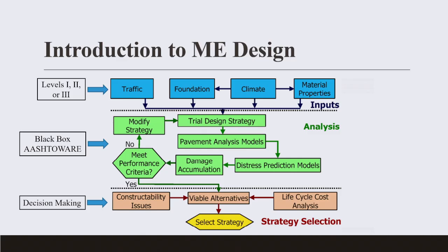I know under the ECOWAS project, PEL, you know, PEL Consort from Nigeria, I know they tried to use MEPDG for some of the sections in the design. Then you also input the material properties and the granular material properties. So depending on the level you are dealing with, if it's level 1, then you have to do a lot of laboratory tests to confirm your material properties to be able to input into it.